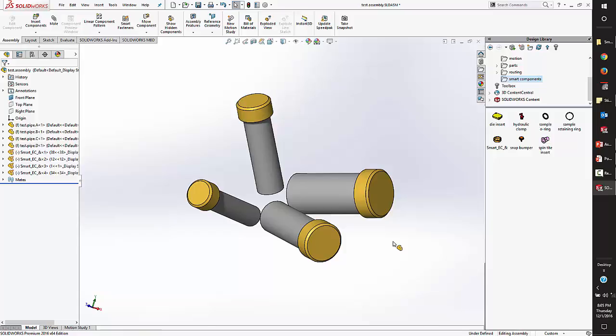So that's one of the things it can do. It can do this auto sizing, and it's pretty straightforward. One of the other things it can do is that this is a single part that's being auto sized. You can do this with assemblies as well too. You can have a part with configurations and an assembly with configurations, and it will automatically update depending on what it hits. So not only will it do with parts, it will do it with assemblies.